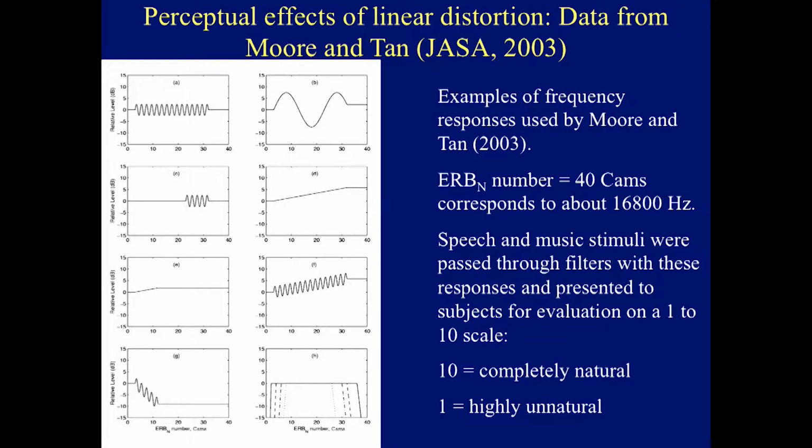They're common in headphones. You also get them in hearing aids, for example. It's quite common to see ripples in the frequency response. They're not usually regular like this, but we thought it would be interesting to include these regular ripples and make them either rather rapid ripples in the frequency domain or much more coarse ripples. And we applied them over a wide frequency range or over certain limited frequency ranges as well to assess whether ripples are more important in any particular frequency region.